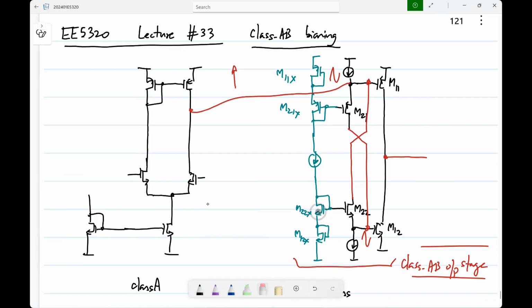So this is a replica of this. First of all, the main output branch is that one. So let's say you want a pretty large current, 5 milliamps through that. So you may put 5 milliamps through this one. Through this branch, I'm just pulling some number out of the hat, it could be 500 microamperes. But these branches could be taking only 50 microamperes or 100 microamperes. But you just make sure that the size ratio is appropriate. That's all.